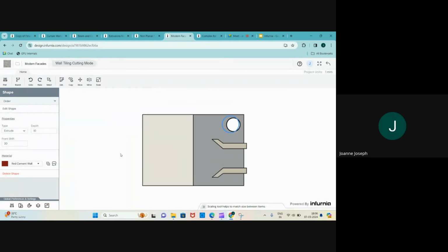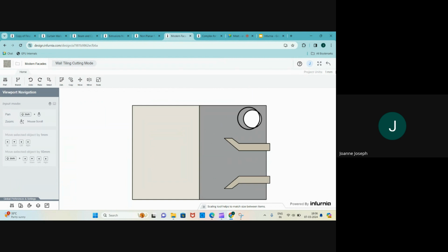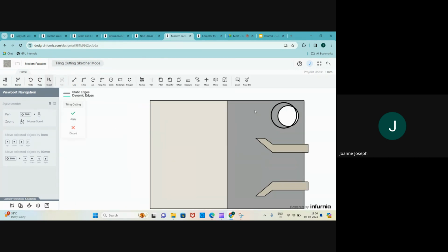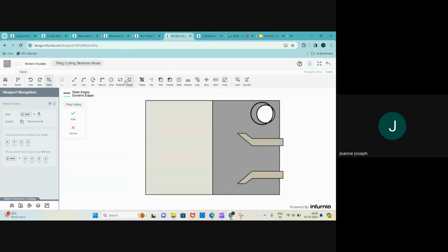So yes, back to the hexagonal shapes. Of course, we have the option to create several sided polygons. If I select add, I will just be selecting polygon here, the same way I clicked on rectangle. And you can determine the number of polygon sides. I want a hexagon, so I'm typing in 6.